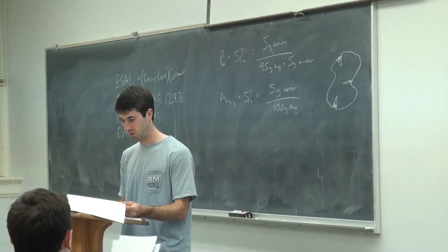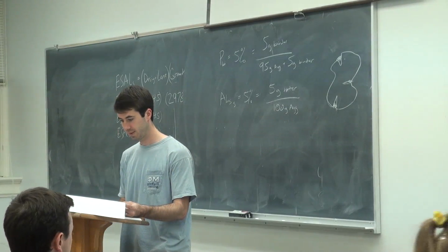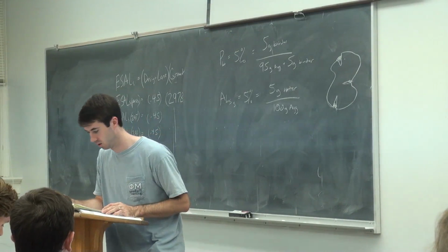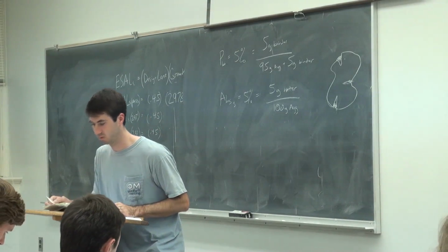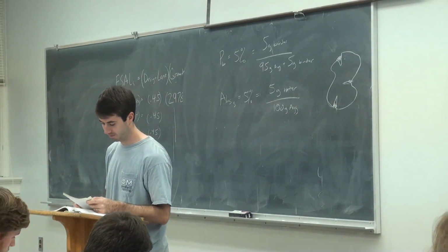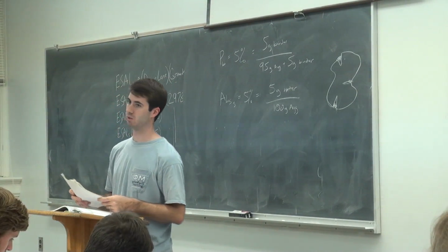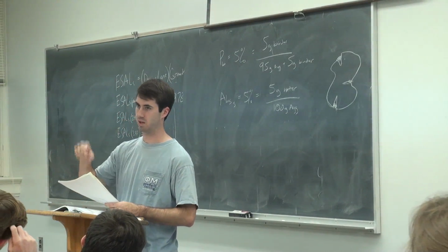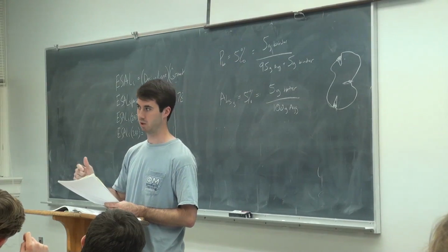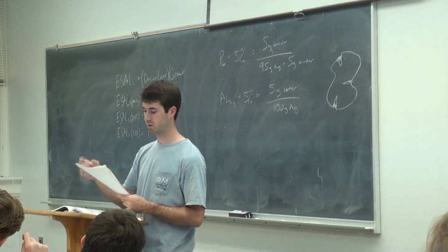Let's see. I guess, nominal max aggregate size. Just because somebody taught me really hard on this in materials lab one day. Keep in mind that you would go to the first sieve size that retains 10% or more, and then you go up one, and that would be your nominal max.